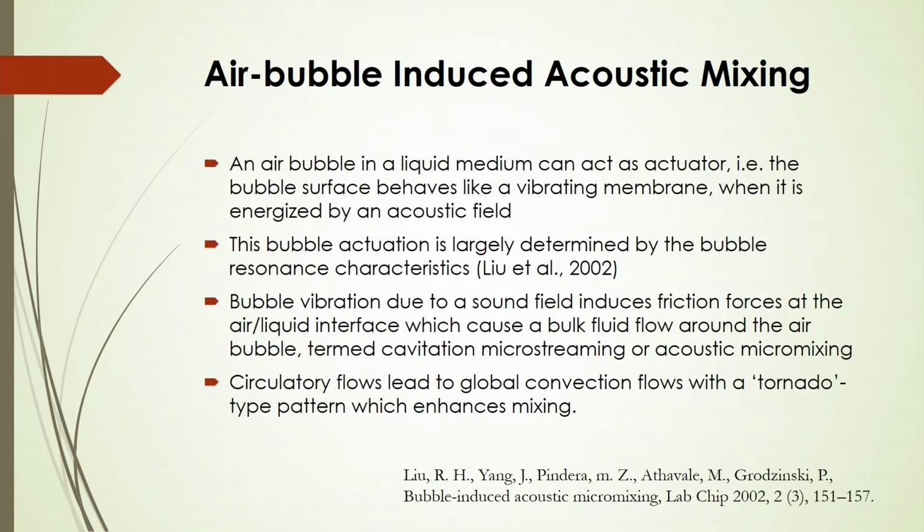Now, another important micromixing phenomenon is called air bubble induced acoustic mixing. An air bubble in a liquid medium can act as an actuator. In this case the bubble surface behaves like a vibrating membrane when it is energized by an acoustic field, and the bubble actuation is largely determined by the bubble resonance characteristics.